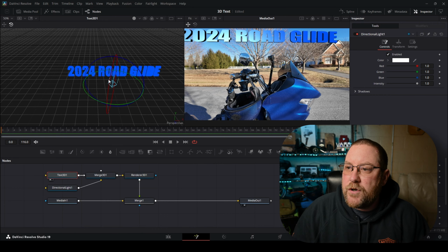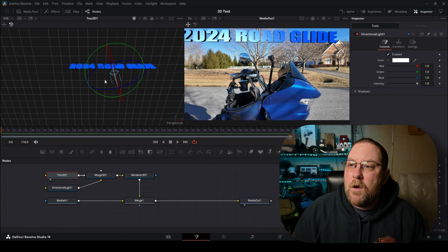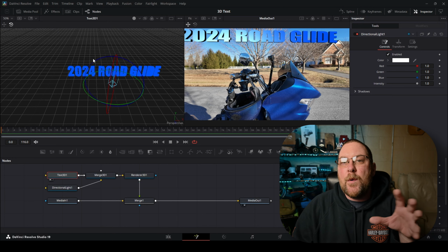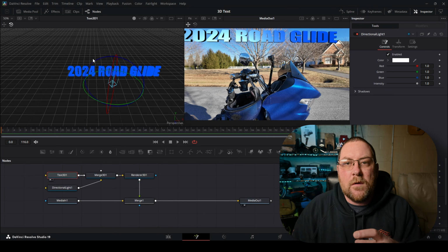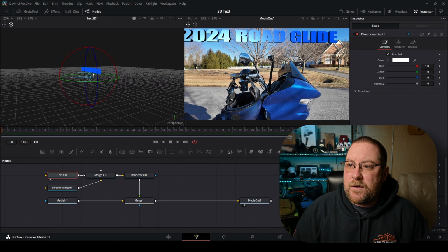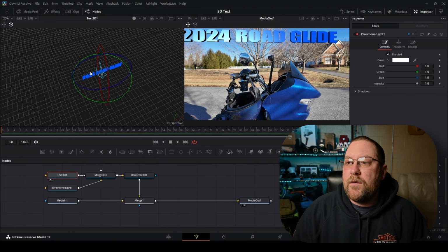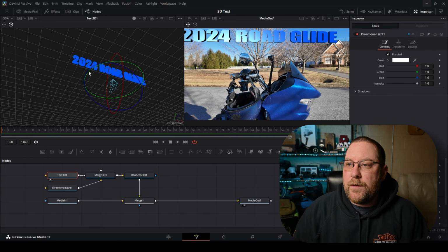And then if we hold Shift and scroll with the center mouse wheel, you can see that we're changing our position relative to where the text is going to be. So nothing on the text changes, but it kind of can help you fine tune where things are positioned by giving yourself a better view. And if you want to rotate, that's as easy as holding Alt and Shift on your keyboard and scrolling with the mouse wheel. So we rotate in one direction with Shift Alt, and then another direction with Shift, and then zoom in and out with Control. Hopefully now you have better ways to fine tune the positioning of things and get a better feel for what's going on in your scene.